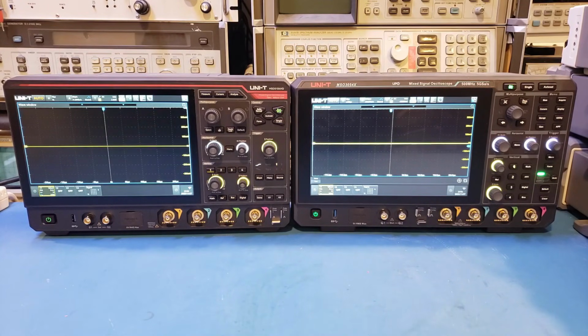By the way, the MSO5104HD also has the enhanced resolution mode, or ERES mode, which can further enhance the vertical resolution up to an additional 4 bits. This gives you a maximum enhanced resolution of 16 bits. Now, this is actually achieved through post-processing, as the ADC is only capable of digitizing 12 bits. As a result, the trade-off of the ERES mode is that the oscilloscope bandwidth is greatly reduced. So let me show you that.